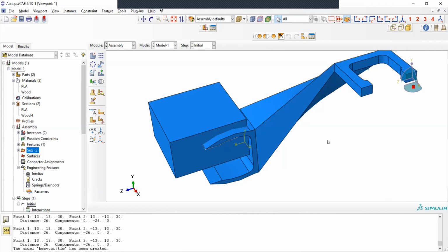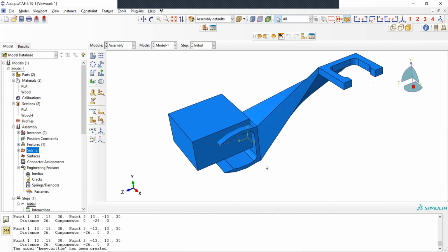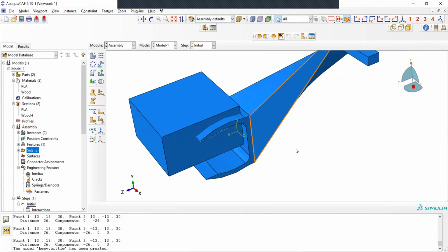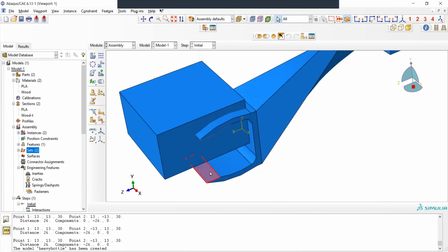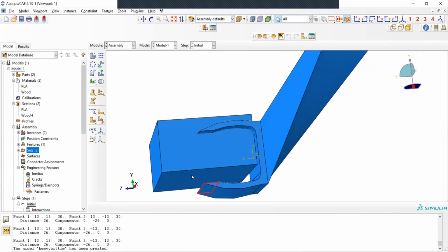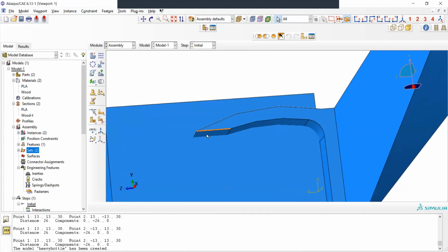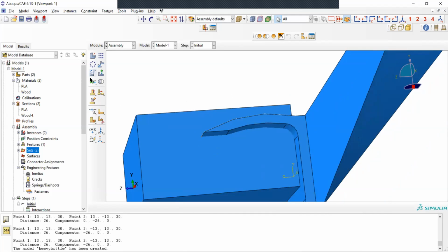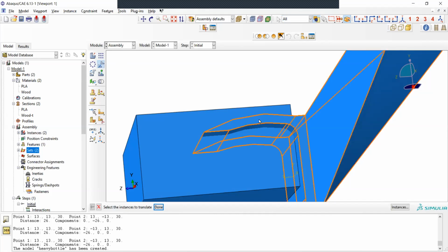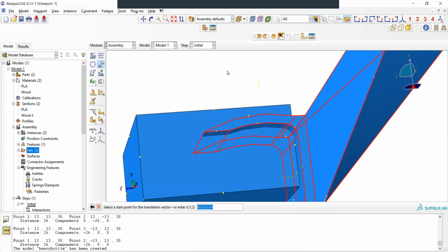And this is a nice thing in Abaqus. It's actually not that difficult to do that. There are 2 ways, and I will use them both. First, I want this surface here to touch the bottom of the table, or this surface here, of course, obviously, to touch the top of the table. So what I do is, I go to this feature, translate instance, meaning moving the instance. I click on the part I want to move. I click middle button. Then I tell the software that I need this dot here to be at this position.